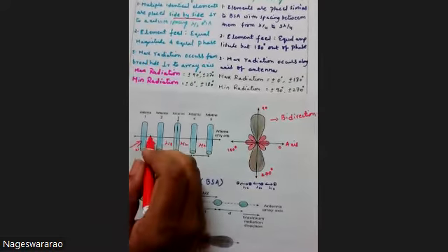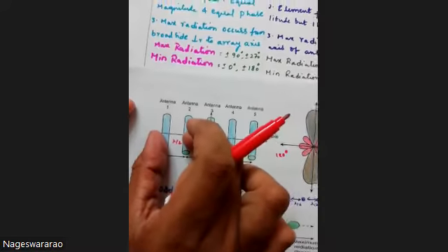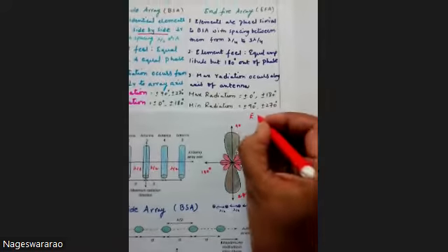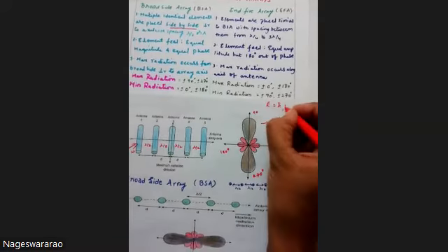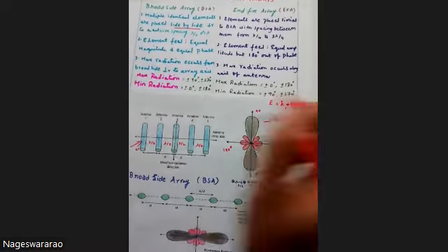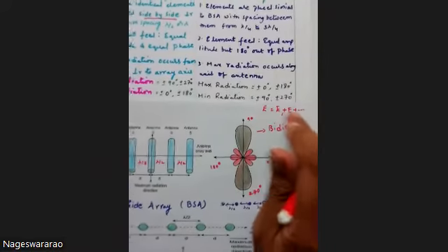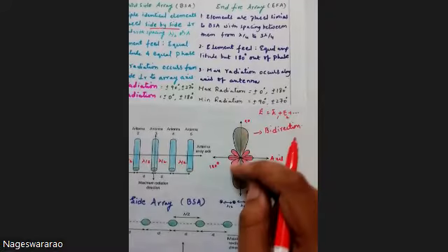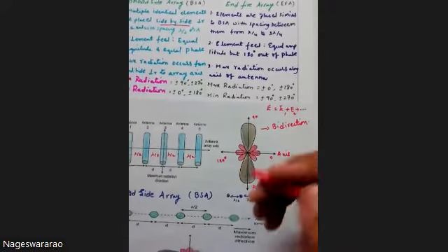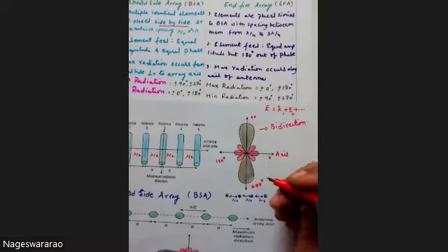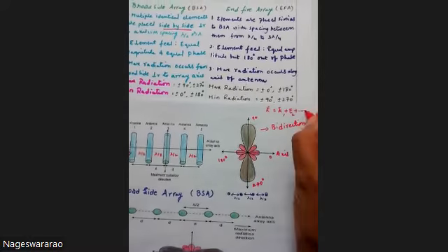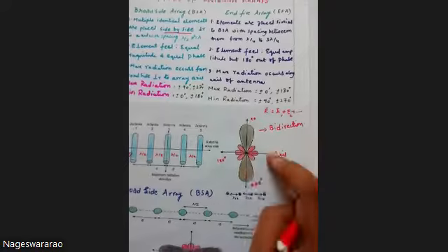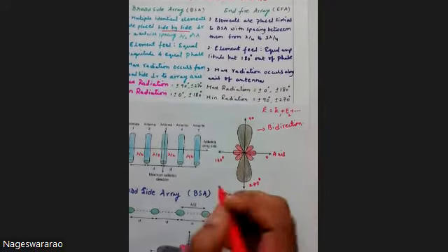See, if you go for the case of two element array sources, we will be adding the field elements. Everywhere the total field strength is nothing but the summation of all individual field strengths. So if you add up all these field equations, finally we will obtain the maxima at 90 and 270. That is the mathematical part also. If you need, I will provide it in another video also. So by adding all these field strengths, we get our maximas here and minimas here. Right, this is regarding the broadside array.